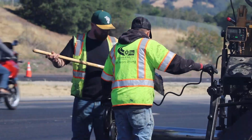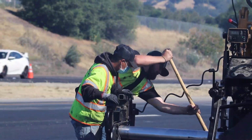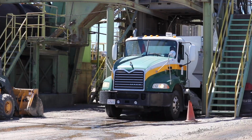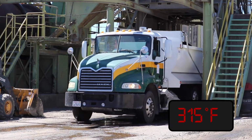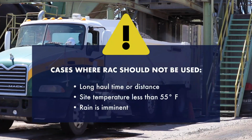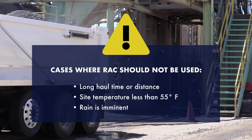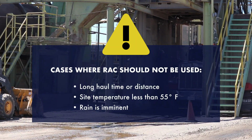It should be noted that high-viscosity RAC mixes are very sticky, have a rubber odor, and are not conducive to large amounts of handwork. Materials must leave the plant at a minimum of 315 degrees Fahrenheit. Tarping of truckloads is generally specified. RAC may not be the best choice on projects with the following conditions: long haul time or distance, site temperatures less than 55 degrees Fahrenheit, or if rain is imminent.